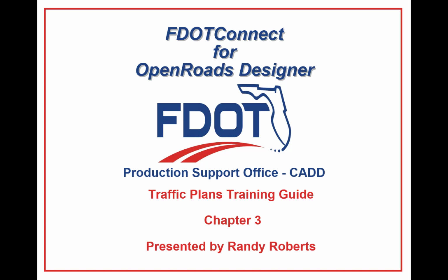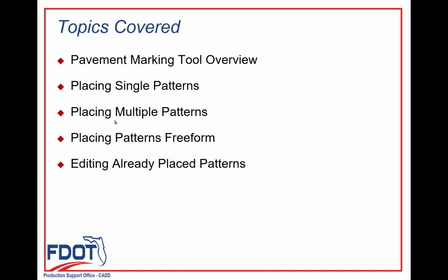In this series of videos, I will take you step by step through each exercise from the course guide. Today, we will start with Chapter 3 of the course guide, Pavement Marking Tools. Topics covered in this chapter will be the Pavement Marking Tool overview, placing single patterns, placing multiple patterns, placing patterns freeform, and editing already placed patterns.